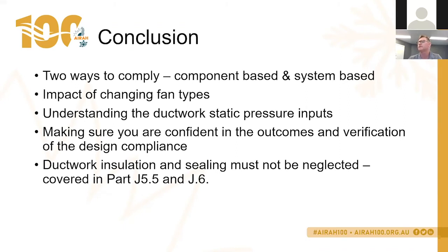For low pressure fans, it is the system pressure in the calculation. So it's the same as we went through and did the system pressure calculation in accordance with the higher pressure fans. It's the same for the low pressure fans as the system pressure. So it's not just the external static, it's the system pressure.